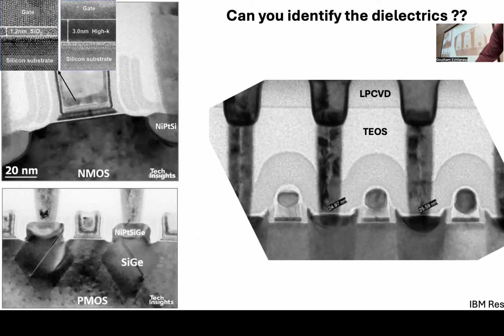For ALD, in this class we talk about thermal dielectrics only for diffusion. But because ALD deposition is at low temperature, you're not sure if the precursor and the co-precursor are fully reactive. So usually after ALD deposition, there will also be an annealing step. Okay.